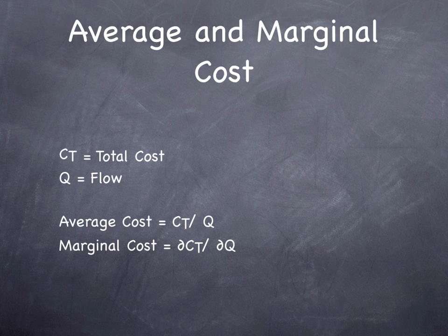The marginal cost is the cost of delay that they're imposing on everybody else. So you can think of this as an incremental cost, the difference in total cost with and without the vehicle. That is the average cost with the additional car multiplied by the number of people experiencing that cost minus the average cost without them, multiplied by the number of people experiencing that cost. The marginal cost is the change in total cost over the change in flow, dC/dQ. This should cause you to recall your calculus.